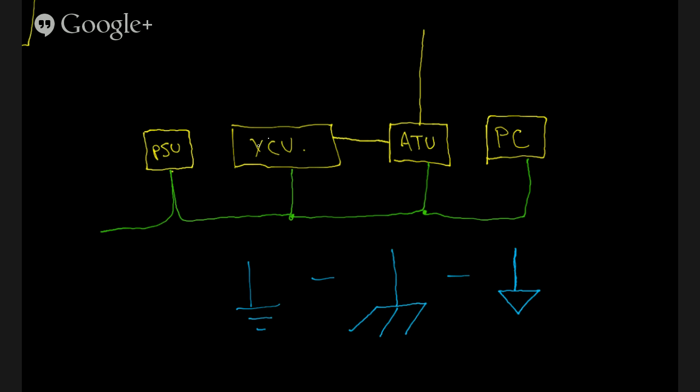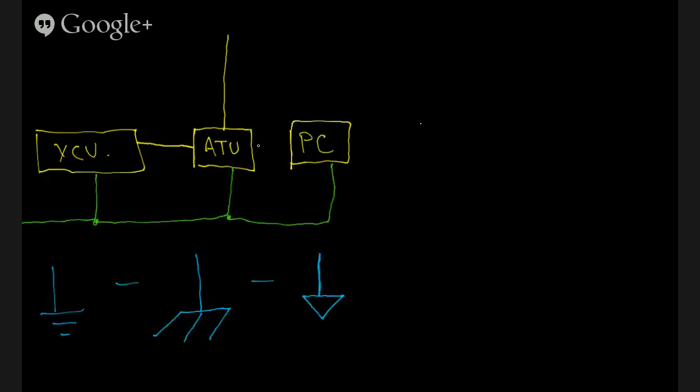With our transceiver here, our transceiver might put out a considerable amount of RF energy, and some of that energy can end up flowing back on the shield of a microphone cable.